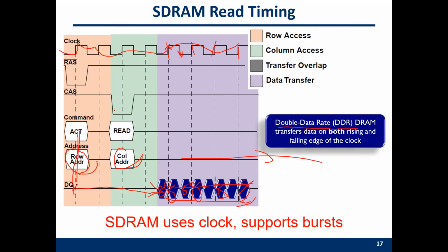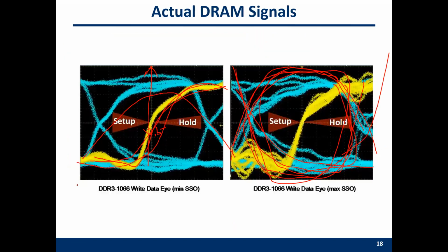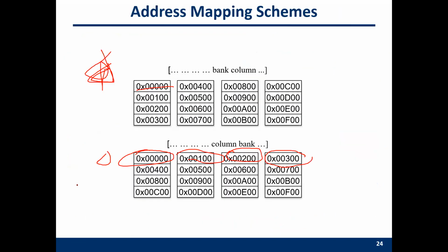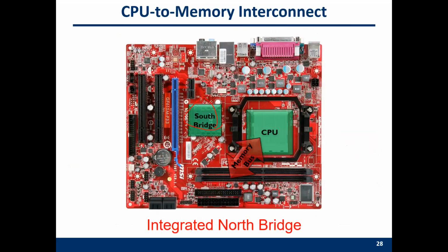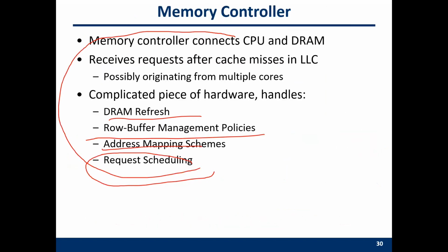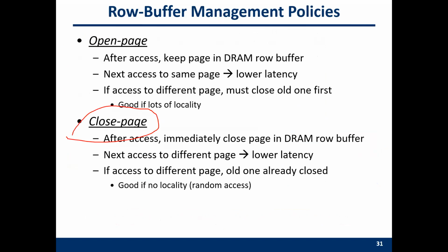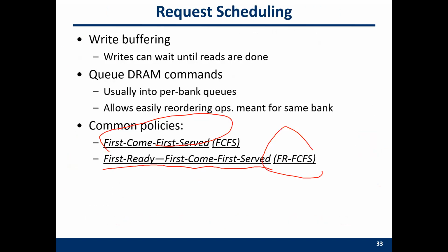Only after you send out the activation, after 2 cycles or 3 cycles, can you send the column address strobe. They have some fixed delays and fixed limitations, and the memory controller needs to remember all these constraints. This is the reason why the scheduling is difficult. Even sometimes you have a buffer hit, but because of some timing constraint, you have to give up the hit.